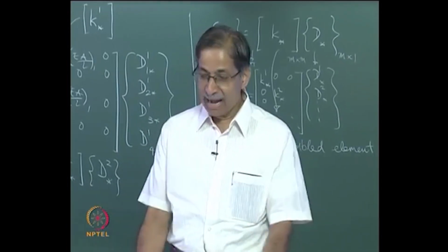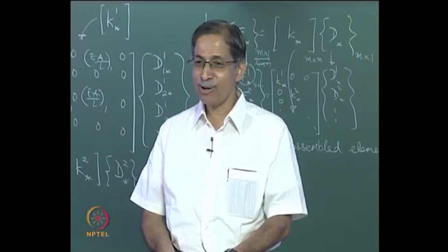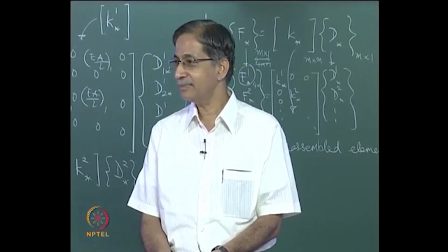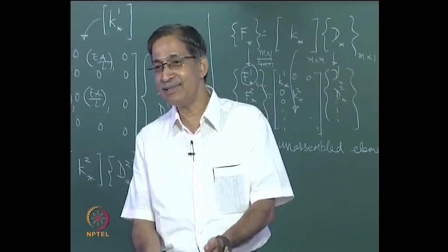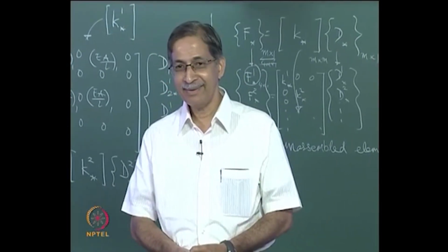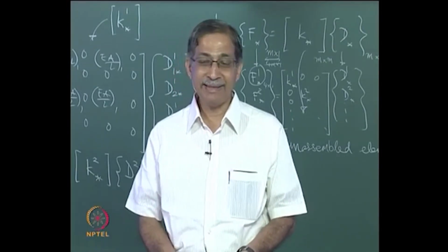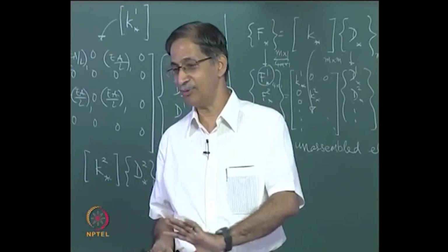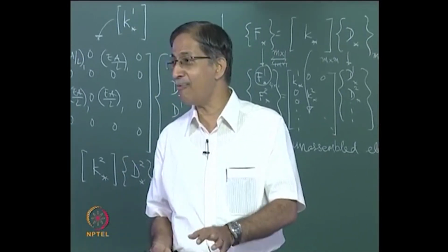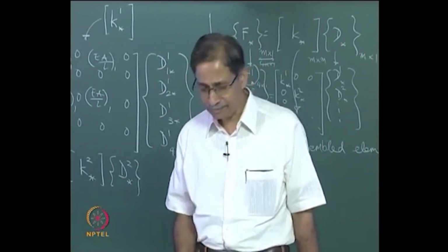Support. See, they are just hanging, floating in the air. How can you build structures like that? If you push them, they will just, this is not outer space, right? So you don't get any unique results. These are unstable structures the way we have drawn them, right? That is the simple reason they are unstable structures. You have rigid body movements, so you have independent displacement vectors, which is fine, but you do not have independent force components in the force vector. That is a simple answer, but there is more to it.